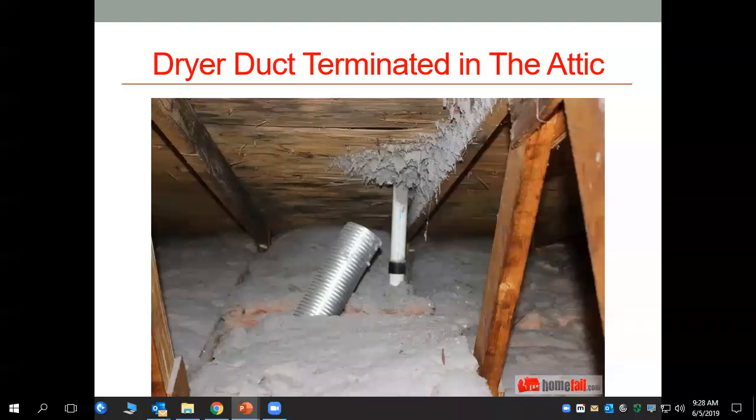And here's one I found that is a dryer vent that was never vented. It was just stubbed in the attic. That's lint on the inside of that deck. And that insulation was pink. That's lint. Lint is a highly flammable product, and that is a fire hazard and a bad thing. And I have personally found that more than once. It's really scary and it's not good.